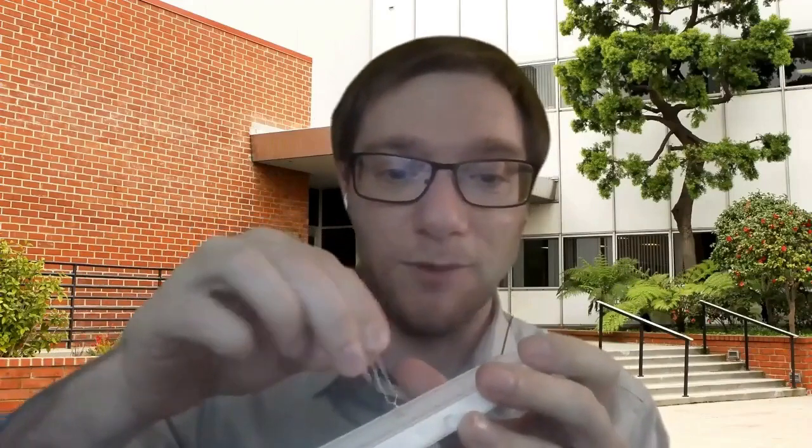When you're pressing this particular piece into this little board, you want to make sure that you grasp the legs very close to the bottom so that you don't bend the legs too much. If you just grab it way at the top and try to press it in, it won't work. It'll kind of bend, and you want to make sure that they don't cross like this and touch each other. So this is going to be one of the more fiddly pieces that you have to be a little careful with.